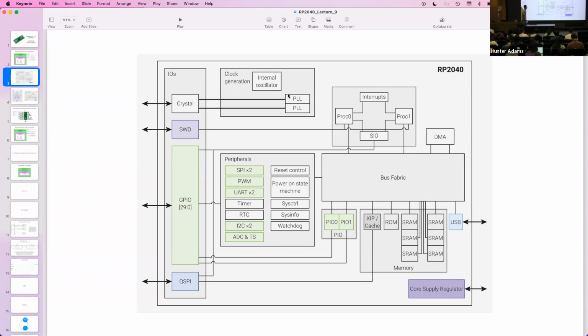There are also two PIO coprocessors. These we'll talk about in detail probably in 2 weeks. But as I mentioned briefly previously, you can write programs for each of these two coprocessors in assembler. There's a custom assembler called PIO assembly for these two coprocessors. They are really limited in a really fun way. The program that you write for either processor may not exceed 32 instructions. That's as long as your program can be for either of these two things.